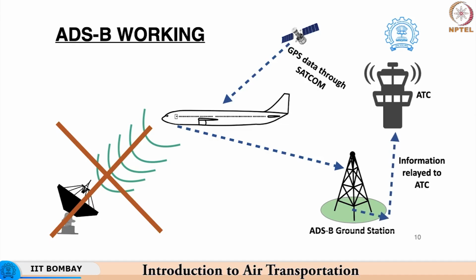So, on the front of the ATC, ATC might have a particular display unit wherein this type of data is readily available to the ATC controller, and based on this communication protocol itself, the overall instructions can be carried out without the need to carry out verbal or voice communication between the ATC and the aircraft itself.